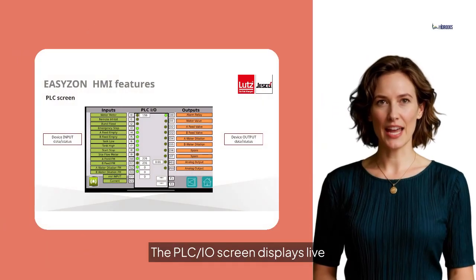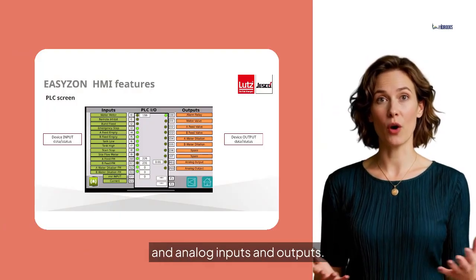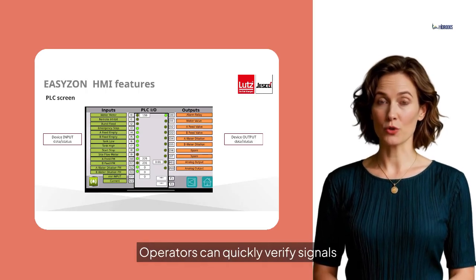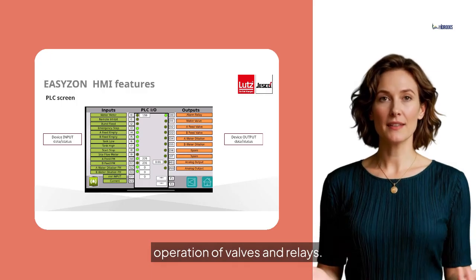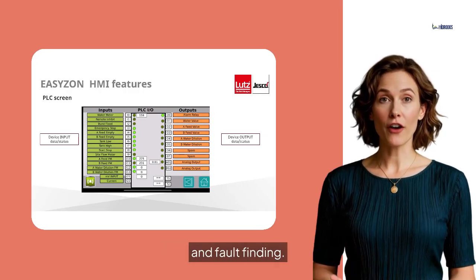The PLC I/O screen displays live status of all digital and analog inputs and outputs. Operators can quickly verify signals from water meters, level switches, and emergency stops, and confirm operation of valves and relays. This is a powerful diagnostic tool during commissioning and fault finding.